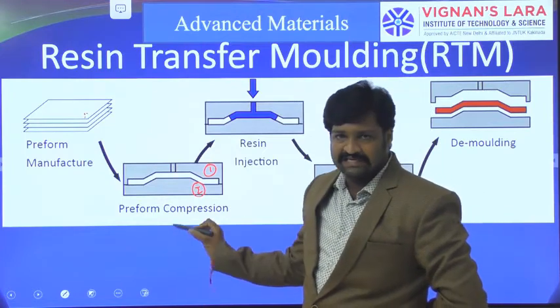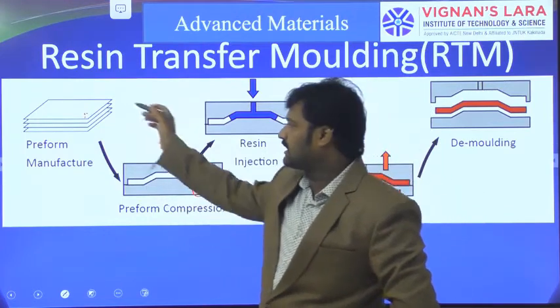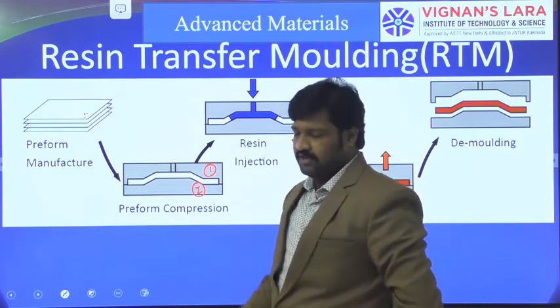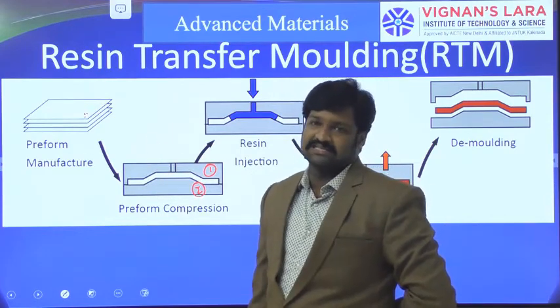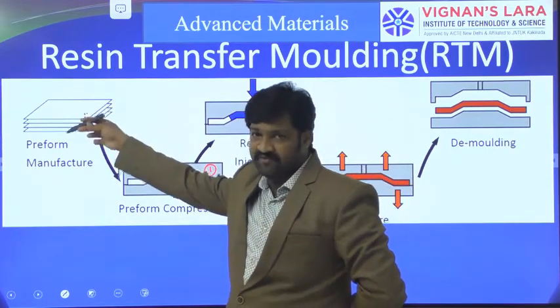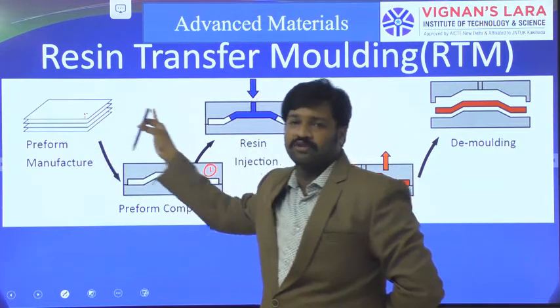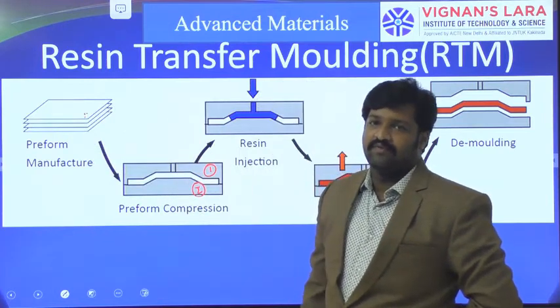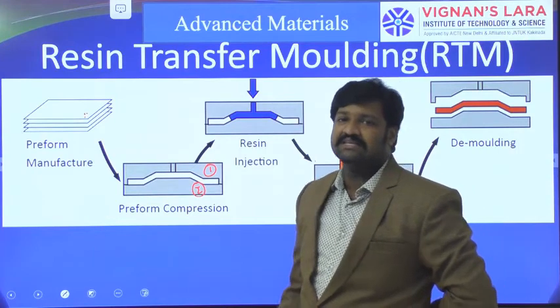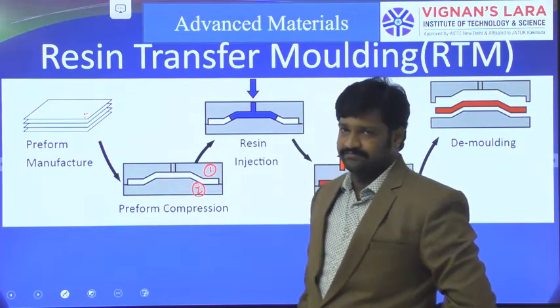If it is a regular, straight surface, we can directly place our fibers onto the surface. If it has some cross sections or shaped features, then we need to press the reinforcement into that shape and transfer it onto the die for easy impregnation as well as easy sitting of our fibers.